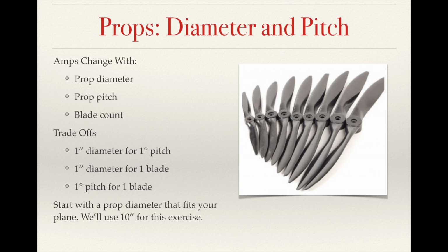You could go to a 9-7, so you could take a 10-6 and drop it down 1 inch and increase it 1 degree of pitch, so you could go from a 10-6 to a 9-7. You can also trade an inch of diameter for a blade.